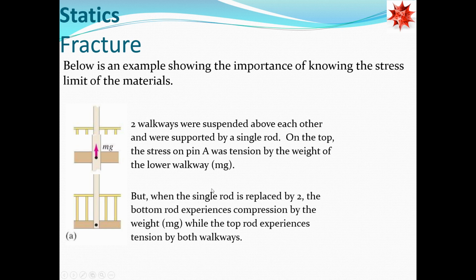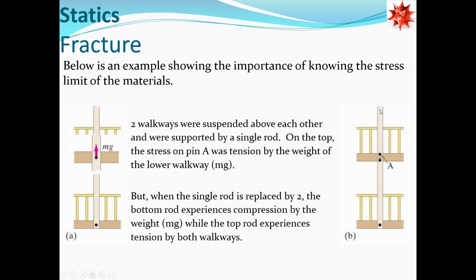However, if we split it up so now there's two beams, a beam up here supporting this and a beam over here supporting this. Well, while the net force at this location will still be the same, an mg going up, it turns out that by splitting into two pins, we actually end up doubling the force that this pin will end up feeling.